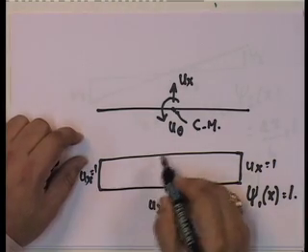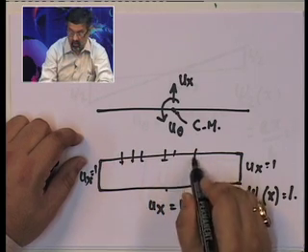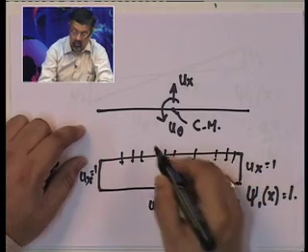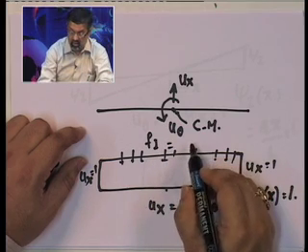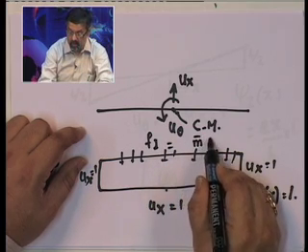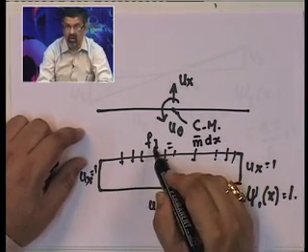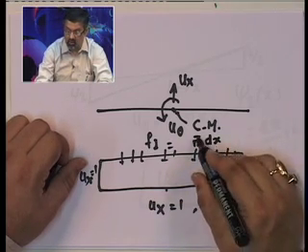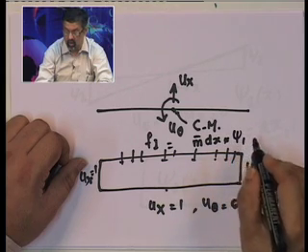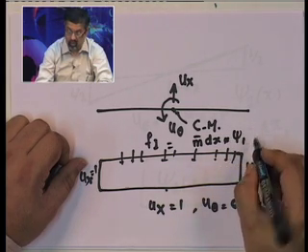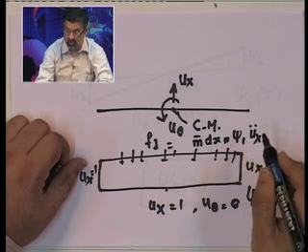Well, I have one which is the F I, which in this particular case is equal to m bar dx. Okay, F I is inertial force per unit length, and that is equal to m bar dx into xi 1 into u x double dot.